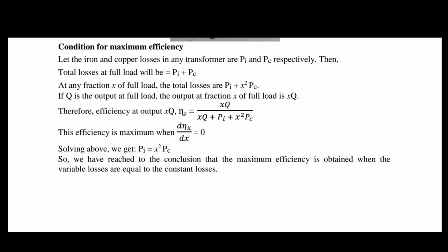So the copper loss is termed as the variable loss, and the losses in the conductors are I square R losses. So these are I square R losses. Okay. So this R is not the load. This is not the resistive load. And since this is I square R losses, this can be I square R or I square X, or in general, we can say I square Z. Okay. But this is not the load.